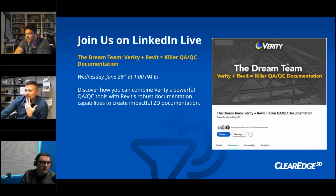So with Verity for Revit, you can use any template to start your project, because what Verity is doing is taking all of its data. When you run the analysis and bring it back into Revit, it's automatically creating all of those parameters and that parametric data. It's adding that in based on the analysis of the point cloud, but it's adding those parameters to the entire category of the element based on what it's analyzing.